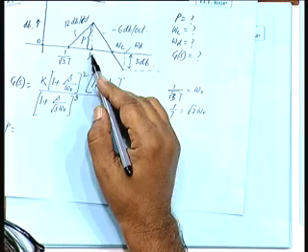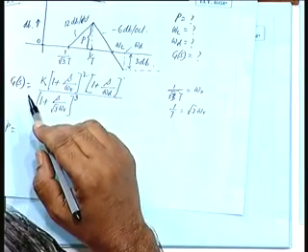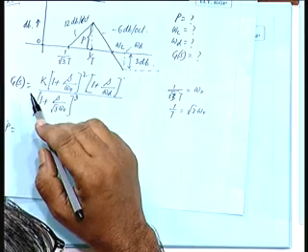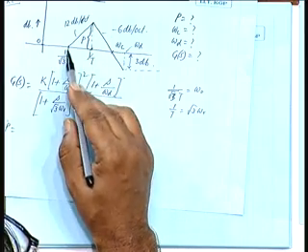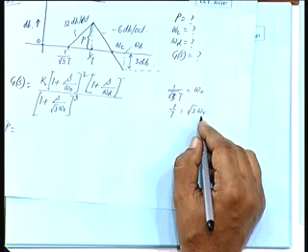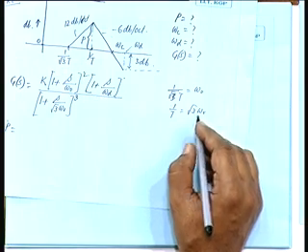It is at a slope of 12 dB per decade. No, at 3 times omega, say at root 3 times omega naught, that means the frequency is increasing by root 3. So, how much is 20 log of 1 by root 3?